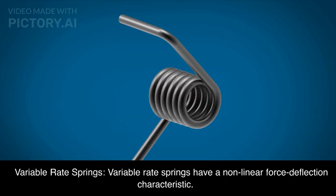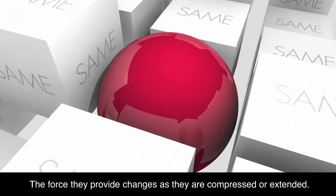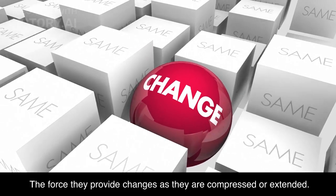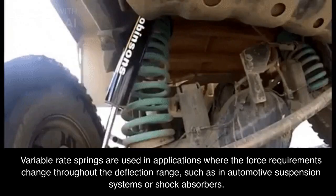Variable rate springs. Variable rate springs have a nonlinear force deflection characteristic. The force they provide changes as they are compressed or extended. Variable rate springs are used in applications where the force requirements change throughout the deflection range, such as in automotive suspension systems or shock absorbers.